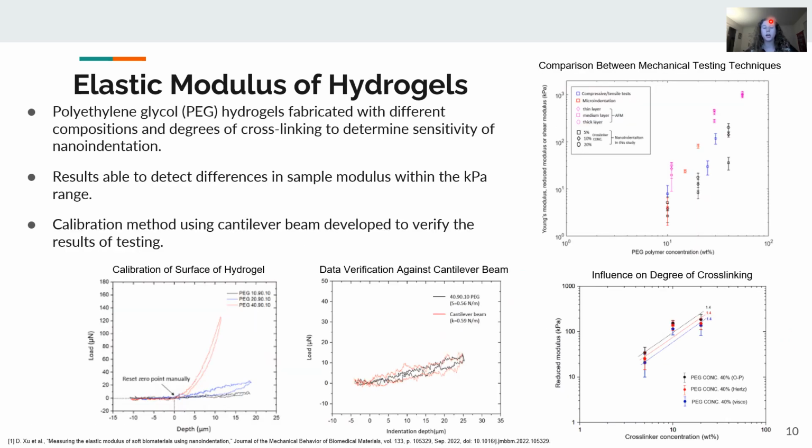Another common issue with nanoindentation of soft or elastic materials is the inability of the indenter to realize that it has already penetrated the surface of the sample. And so work completed by the National Center of Advanced Tribology in Southampton aimed to determine how low of a hardness or modulus nanoindentation can detect and whether or not it can maintain resolution at these low loads.